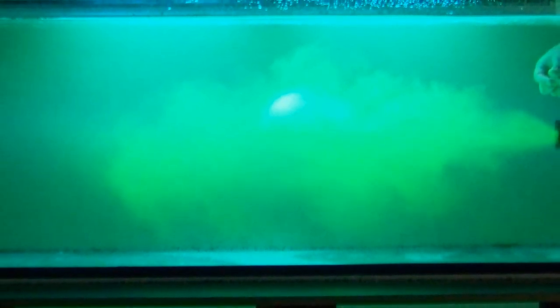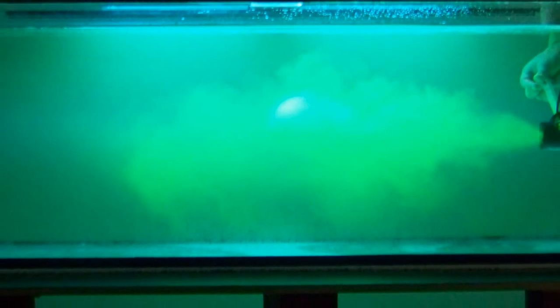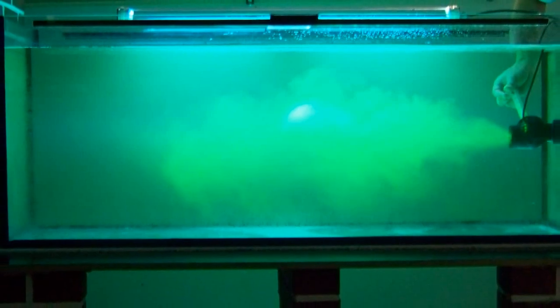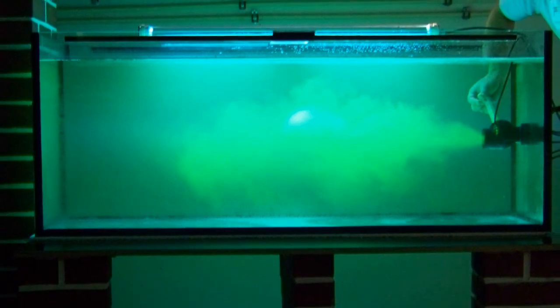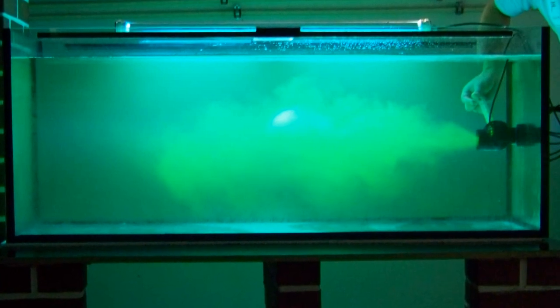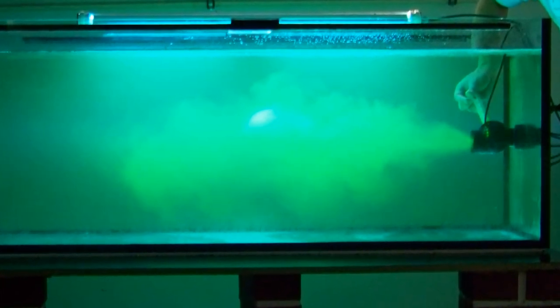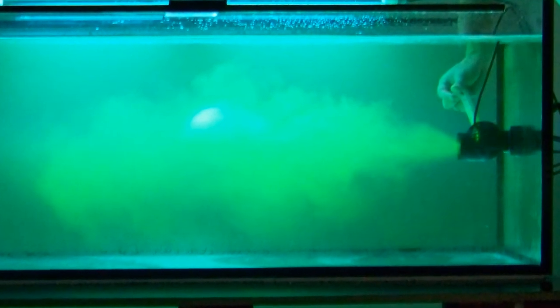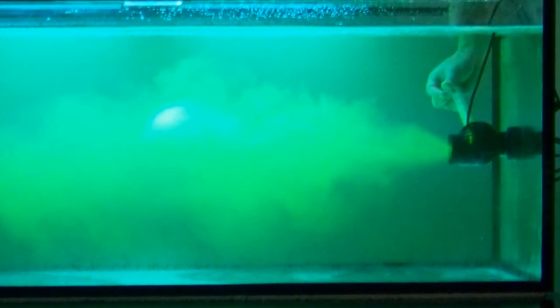It should be noted that transport of dye is an ISO standardized test and is regarded to have an uncertainty of 0.5% when properly performed. This method calculates laminar flow velocity by the time it takes a weak radioactive tracer dye to arrive downstream. While we did not have a sufficient tank length nor access to the radioactive tracer dye required to do the ISO standardized test, we do hope that further independent analysis of flow will utilize this method, and the video presentation effectively demonstrates where there may be errors from relying on standard flow meters for measuring propeller pump flow.